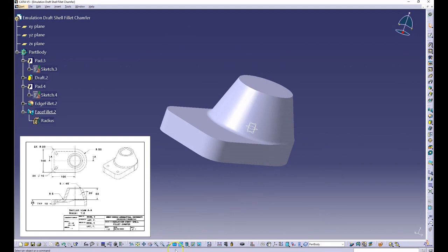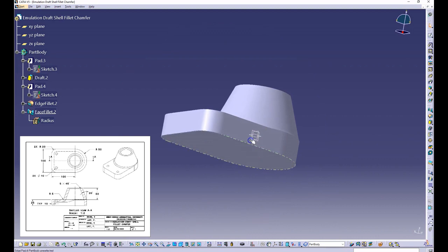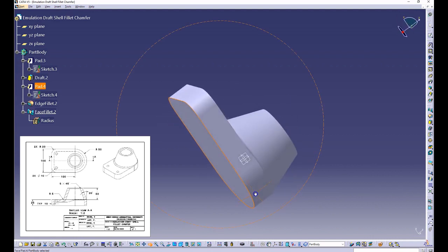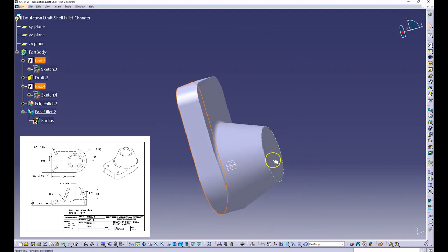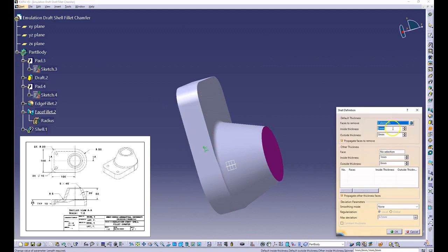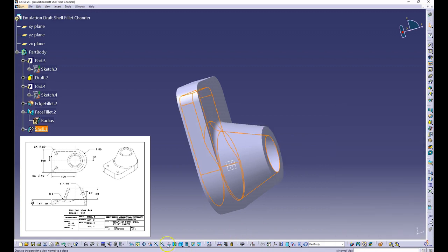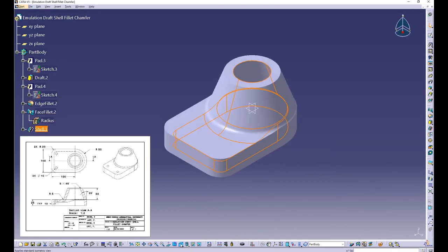By selecting both of those faces together, I can do the shell in one move that is one solid, typical dimension all the way through, but leaves gaps opening on both sides. So here that is 10 millimeters thick, and it's an internal thickness. I could have done an external thickness. That would mess up my dimensions from what I want them to be.